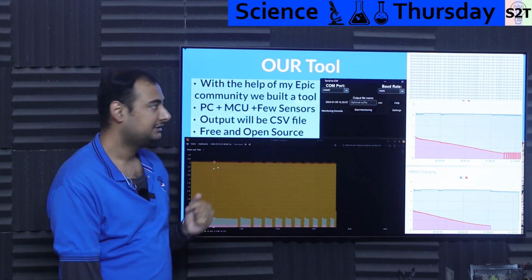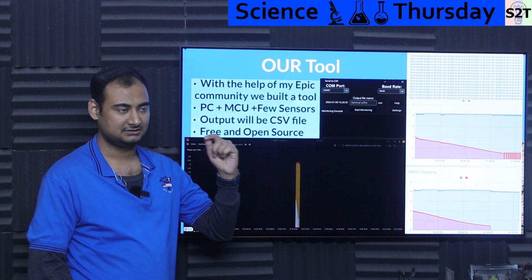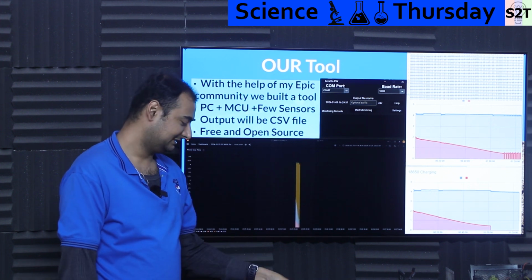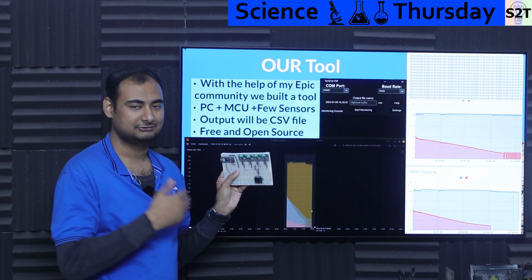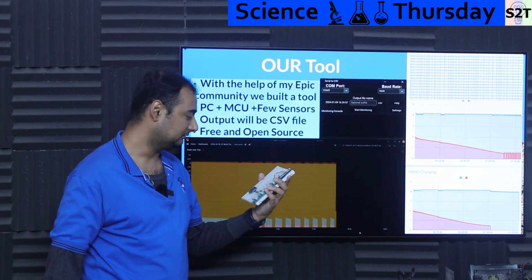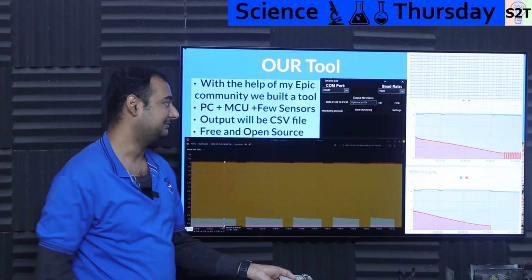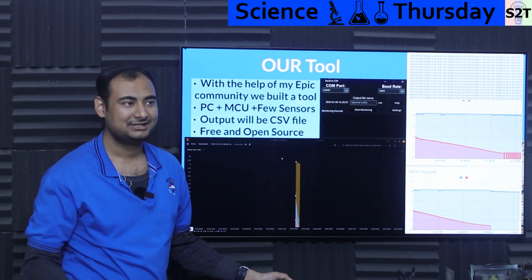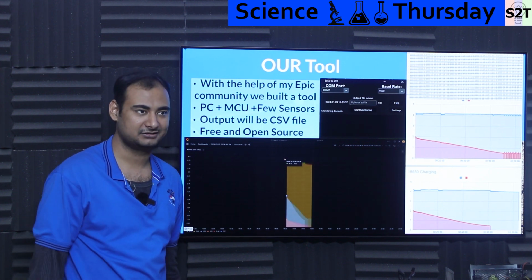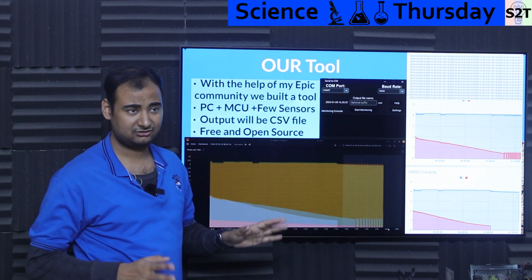What about the refresh rate? I was too optimistic when I was launching this project. I was expecting 1 Hertz, 10 Hertz and 100 Hertz. Yeah, 100 Hertz is not happening. This microcontroller simply cannot read out data fast enough, put that into CSV format and send it over USB. Yeah, that's not happening. And this application is built in Python, so it can barely read at 20 or 30 Hertz. It cannot read at 100. It's not C++. So as data logging, it's more than good enough.